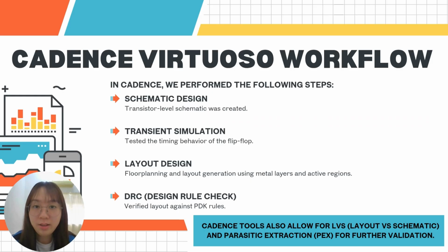Here is the Cadence Virtuoso workflow that we use in our design process. First, we start the schematic design where we create the transistor level schematic for our circuit. Next, we perform transient simulation to test timing behavior, especially important for verifying the flip-flop operations. After that, we move into layout design, where we perform floor planning and generate the physical layout using metal layers and active regions.